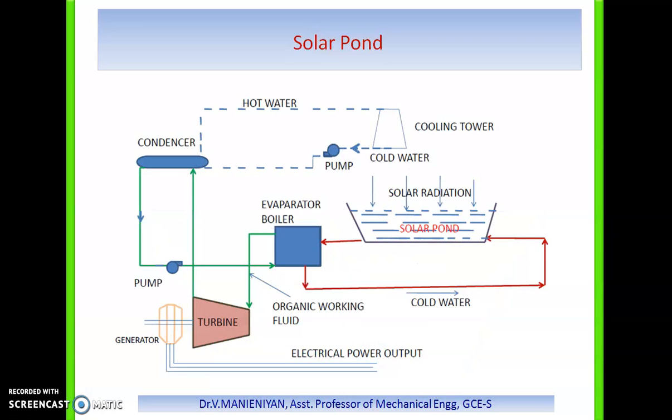So that is the working principle of solar ponds for the extraction of electric energy from the storage system. The energy is stored as low-grade thermal energy in the lower convective zone. Heat extraction is accomplished by withdrawing hot brine and returning cool brine to the zone.